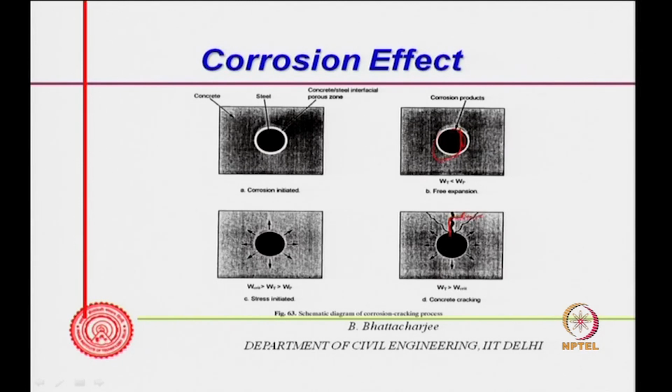So, general corrosion results in cracking of the cover concrete, and this can happen from carbonation or chloride coming from inside, ingredients. But for external chloride, sometimes you may have pitting corrosion. If in one place the chloride has gone, in another place it has not gone, at that location pit formation will be there, and the rebar may actually be lost totally. This could be very dangerous in pre-stressed concrete, because if the pre-stressing wire loses its dimension, it is under stress, and it may even cause a brittle kind of failure.